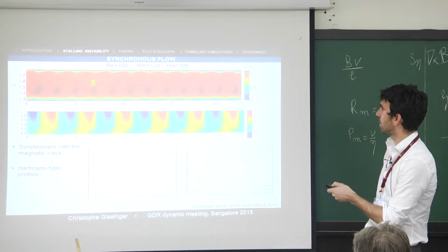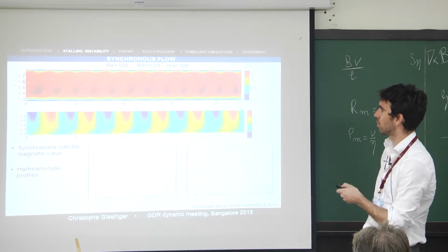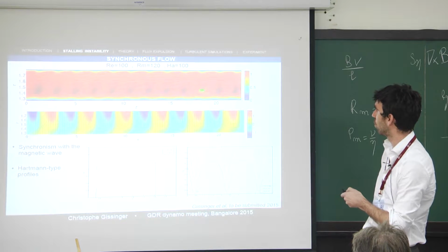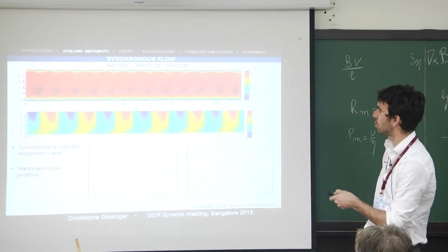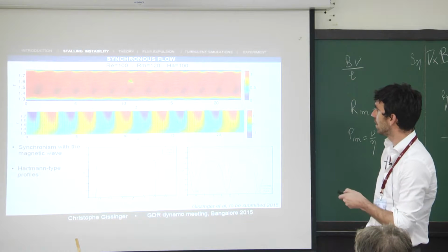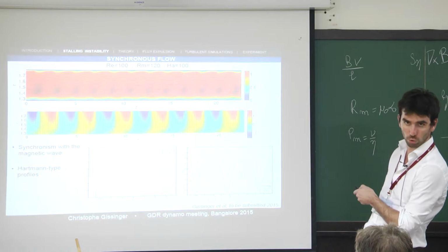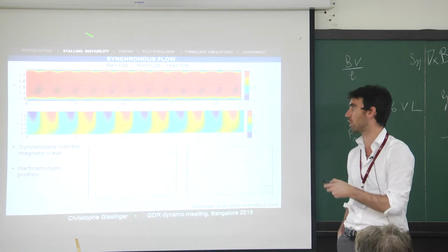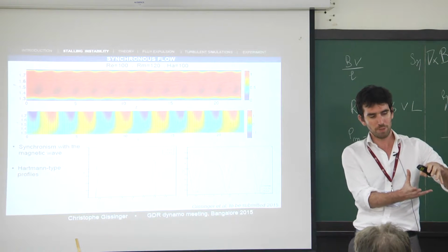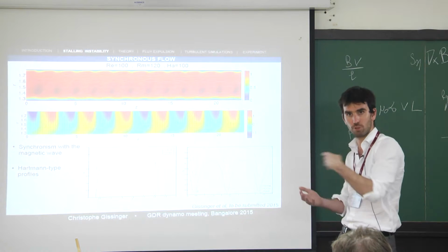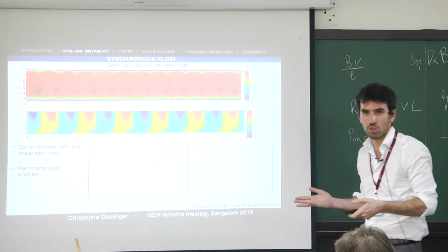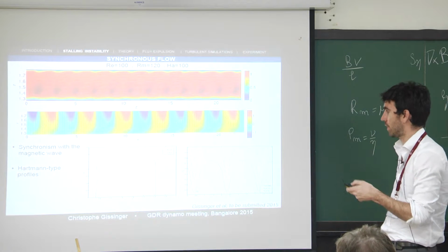And in the simulation, you obtain this kind of flow for low magnetic Reynolds number. First, you can see it's quite homogeneous, except in the boundary, for the boundary condition. The value, if you look here, is close to 1. So it means that for this value, the fluid is pumped nearly in synchronism with the electromagnetic wave driving the motion. Very efficient state.